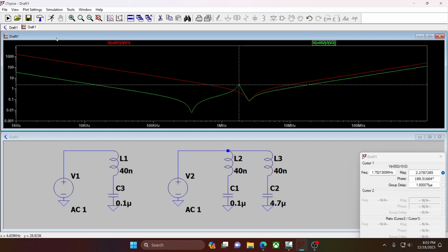All right then. Two things I am not mentioning until now: I started this at 1 kilohertz for a reason. Between 0 and 100, your voltage regulator will take care of those. Those will be very low. And that kind of makes sense because you want your voltage regulator to have low impedance at DC or close to it.